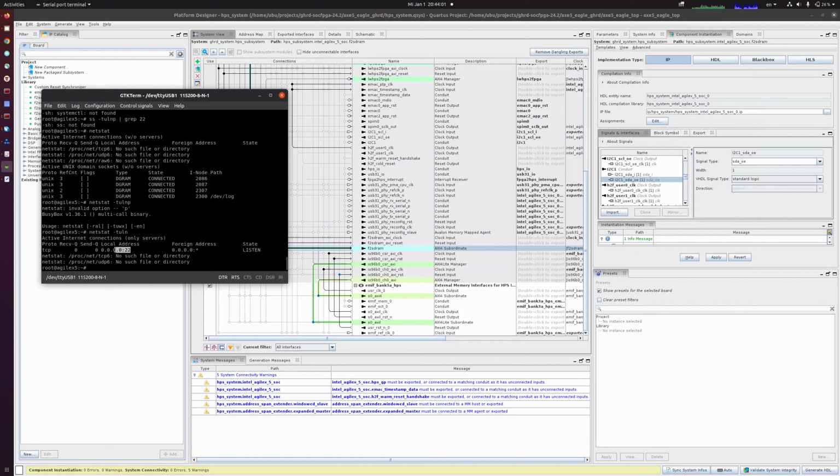It listens to port 22 and 22 is SSH. Good. I can use SSH to connect to this board, but for this I need an Ethernet cable and a USB to Ethernet adapter for my Ubuntu.